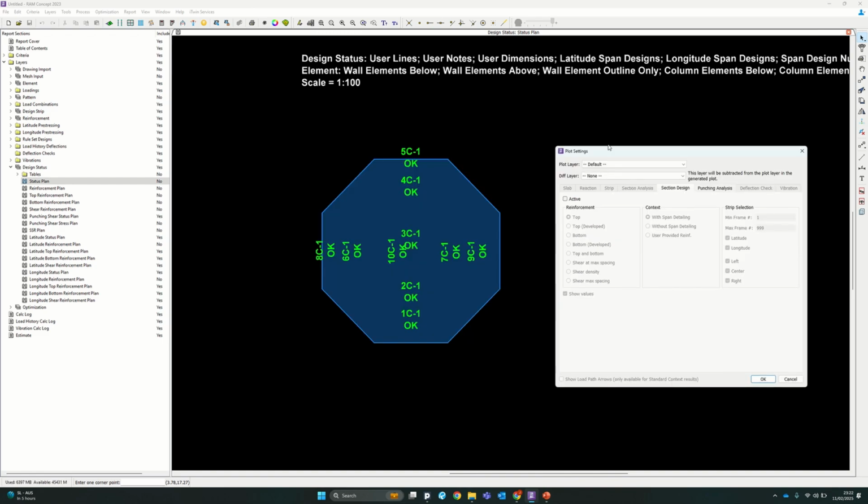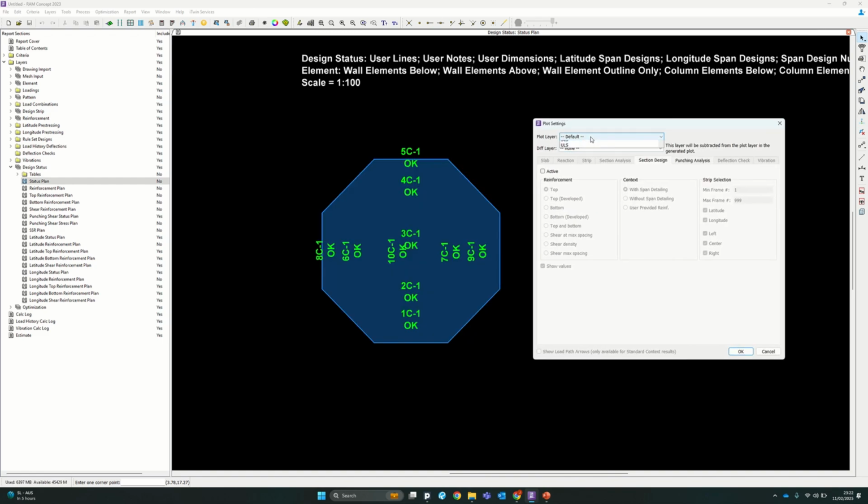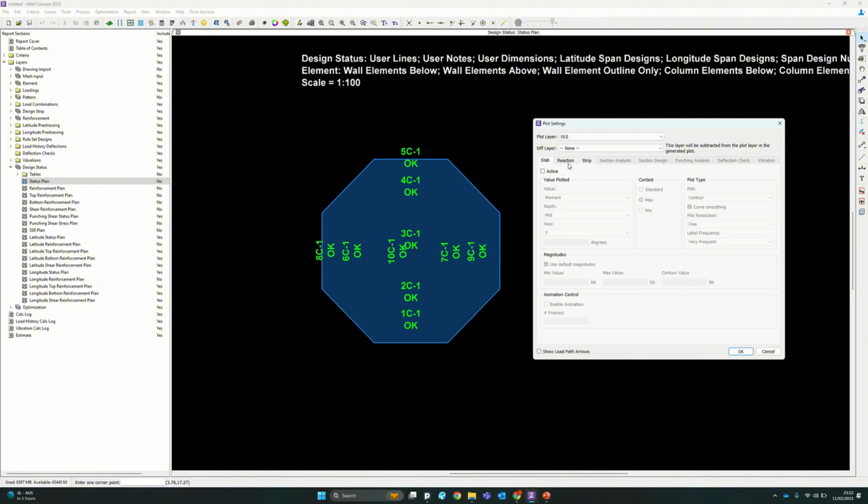So if we go into the plot again and we select the ULS case, oh okay, maybe not for that then. Oh yes, of course. So on top of all these, earlier when we selected the load combinations, we also selected active design rules, and so for the ULS we had strength, accidental and ductility.